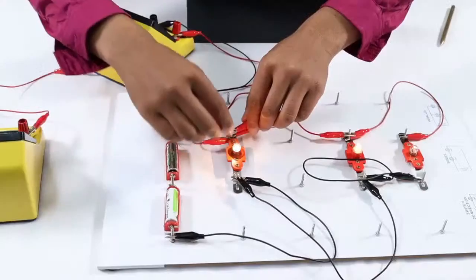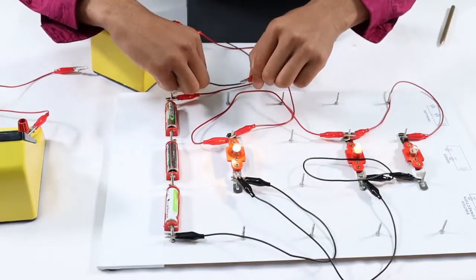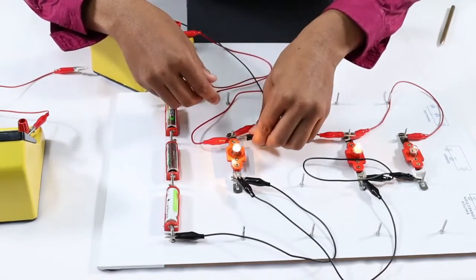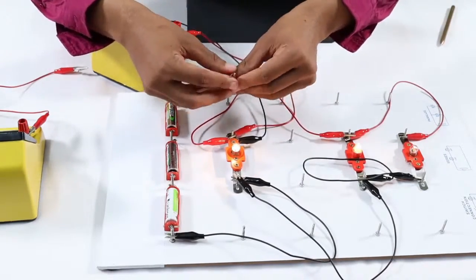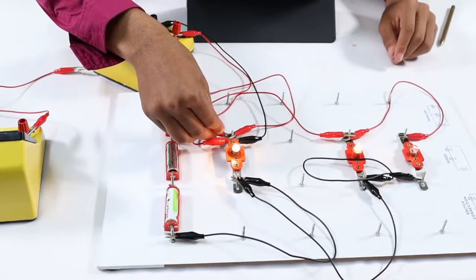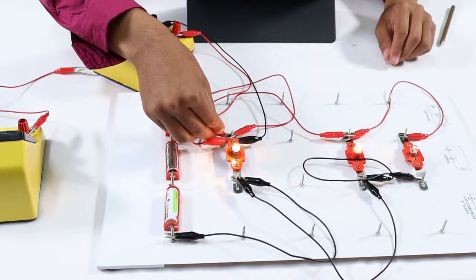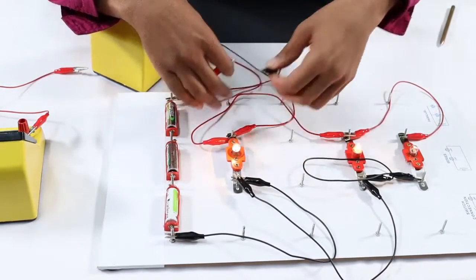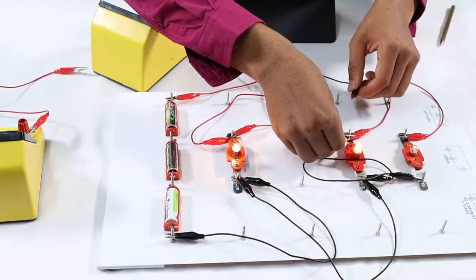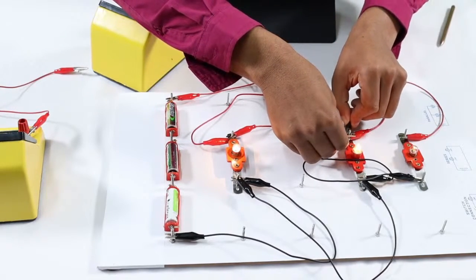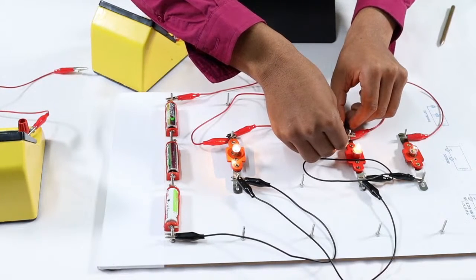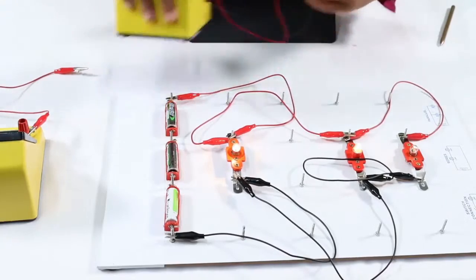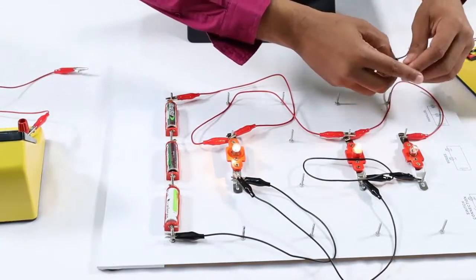Okay. Now let's measure current across the first resistor. I'm going to connect this terminal here because it has to be in series. So it's there, and then it's here. Okay. That gives me a current reading of 3.14. Now let's do the second one. There. That's 1.53. And then let's connect the last one, the very last one.